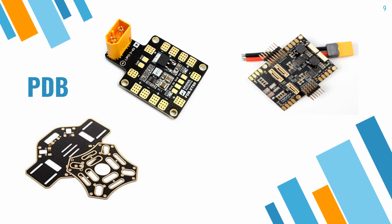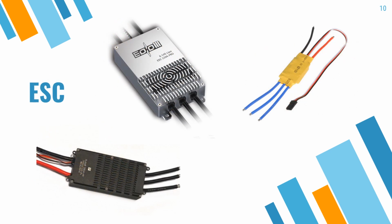This is actually also the one we use for a DronoBox, and besides distributing the battery voltage to the ESCs, it's also capable of supplying a constant 5V and 12V output, which could be useful for other components. The one to the right of it is a more complex PDB, and it's actually a PMB, which stands for Power Management Board. This means that besides distributing power, it's also taking care of signal traffic to all the other electronics.